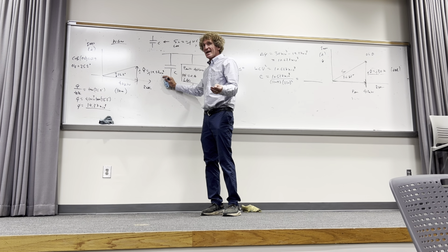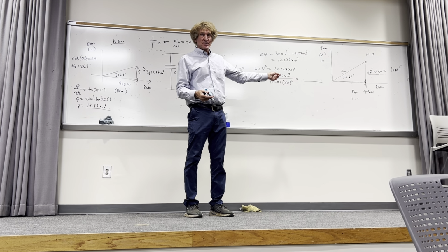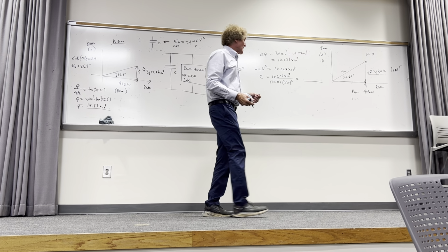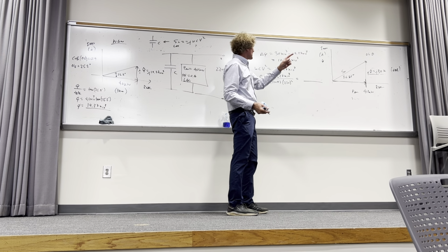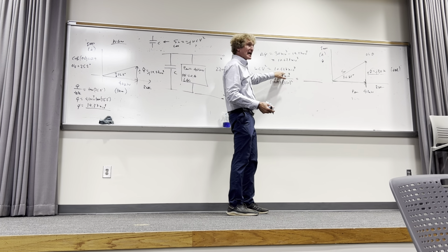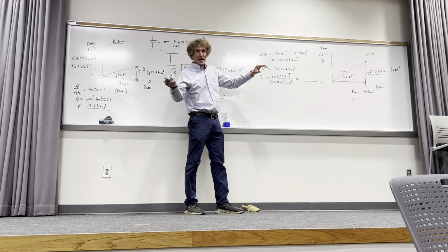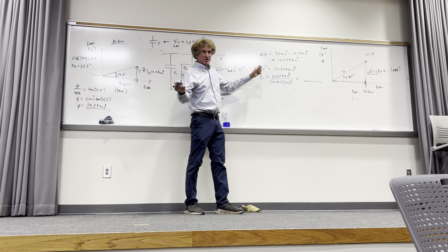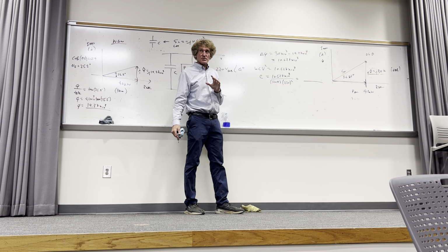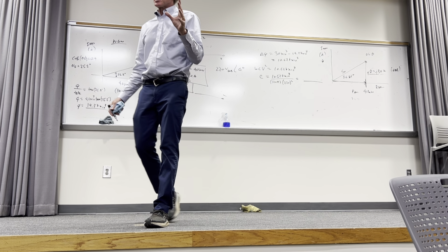The capacitor would be adding a minus J something to that positive J something, and it would bring it down, reducing the total magnitude. So when I got the total difference from the old to the new, I simply knew that had to be equal to the actual effect of the capacitor added, or the complex power associated with the capacitor, omega C V squared. That's right. Thank you, Sydney.